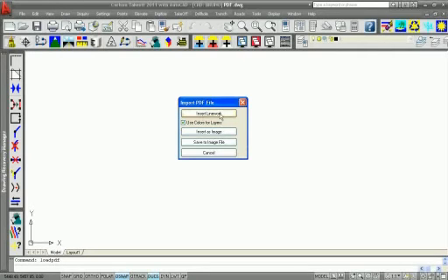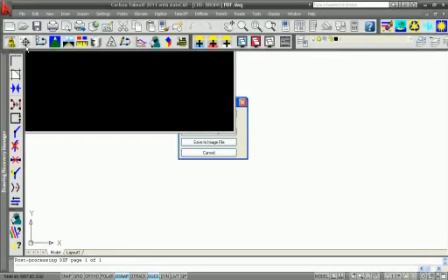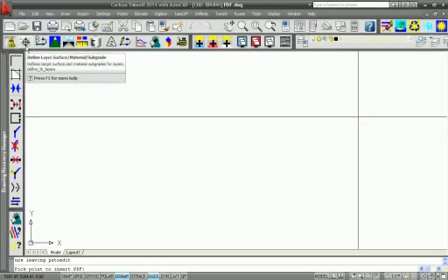So I'm going to say Insert Line Work. Okay, and something else that's new is you see it's saying processing pages 1 through 1, page 1. Before we had a limit of only working with a PDF that had 1 page. Now, if your PDF has 20 pages, you can select which page you want to process and which ones to ignore. And it can process multiple PDFs, and it will just stack them in your drawing. Instead of before, what you'd have to do is open up that PDF and save out a page to bring it in. So we now handle multiple pages on the PDF.